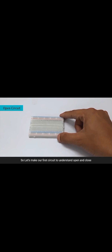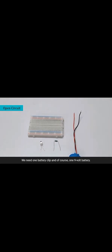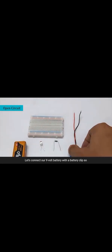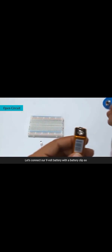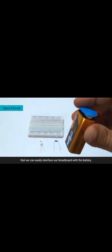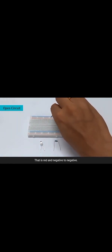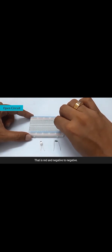So let's make our first circuit. To understand open and closed circuits, let's take one LED, one compatible resistor. Here I'm using a 1 kilo ohm resistor. To power up this device, we need one battery clip and of course one 9-volt battery. Let's connect our 9-volt battery with a battery clip so that we can easily interface our breadboard with the battery supply. So I'm connecting positive to positive, that is red, and negative to negative.